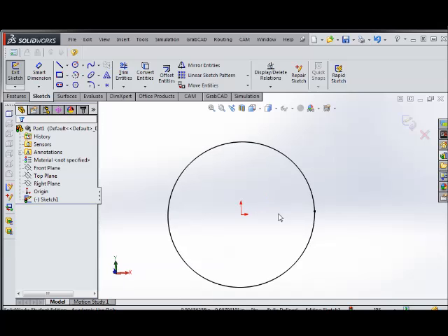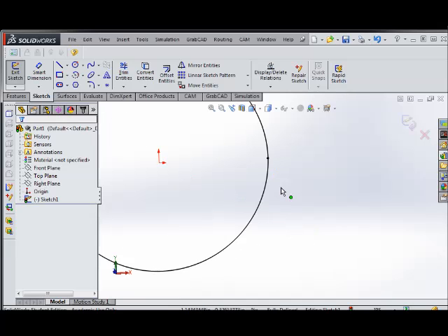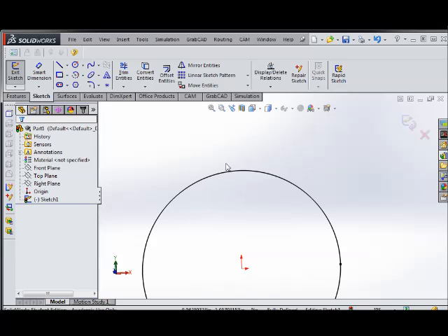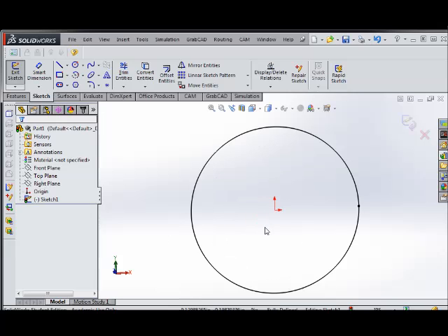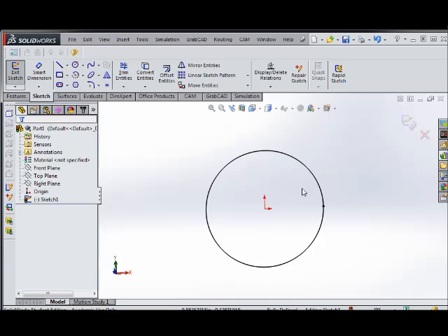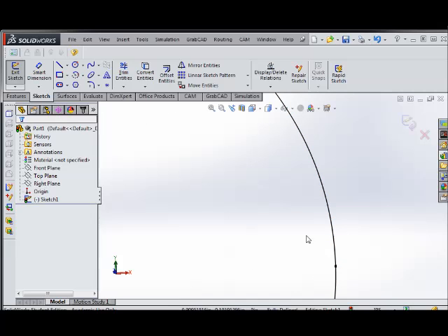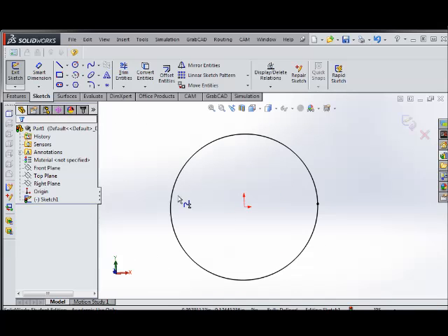Enter those equations in SolidWorks, and we end up with something that's very close to a circle. The only reason this is less than a circle is because I approximated pi. If I tell SolidWorks to use the exact value of pi, it gives me a geometry error because the curve intersects itself, and SolidWorks doesn't like that.